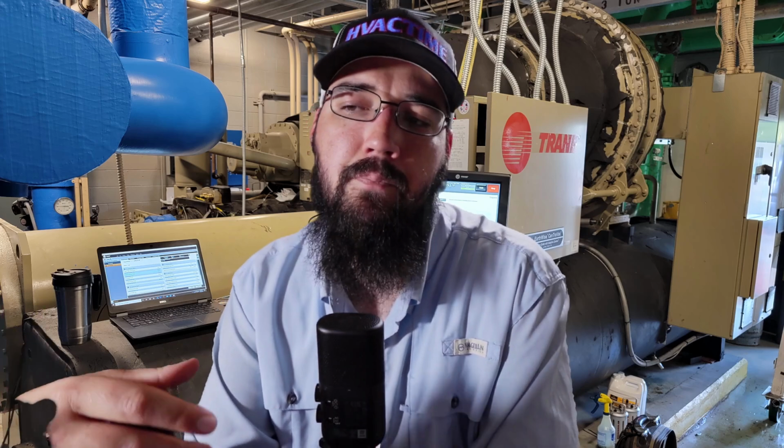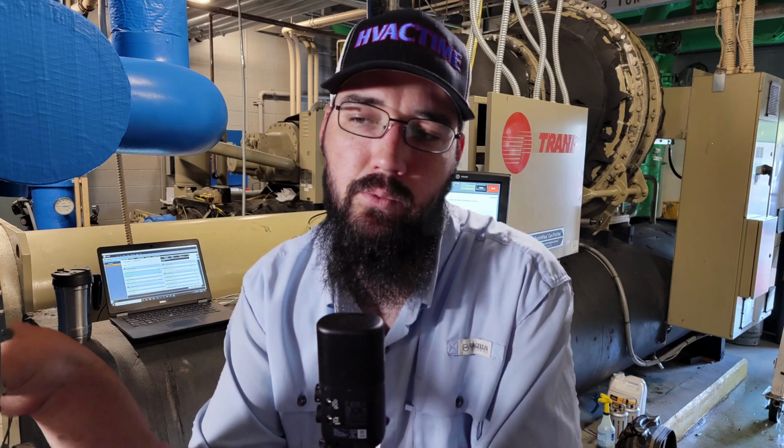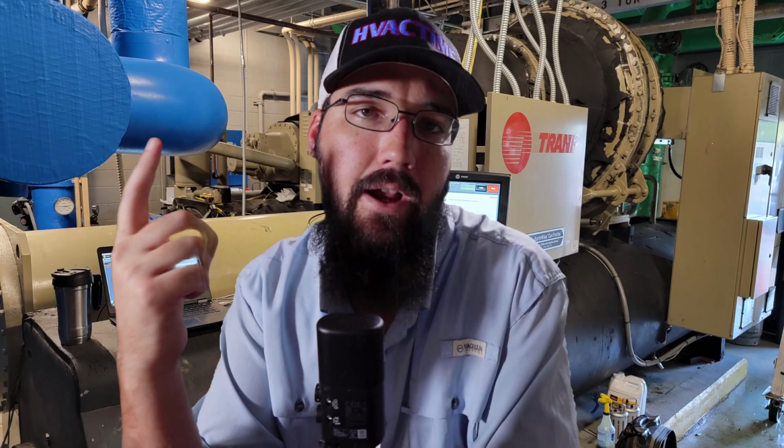So just as another example of, instead of implementing an eductor block, they're using what they call a gas pump. And it's called a gas pump because that liquid drains down and we're using discharge gas to then push or pump that oil laden refrigerant back up into our compressor to recover it. That's the high level details there on that particular setup.